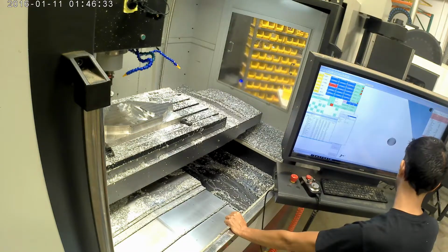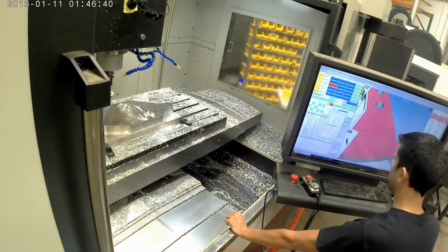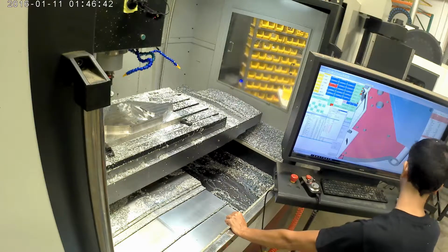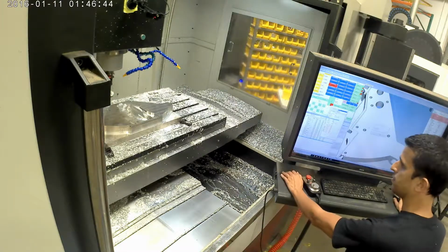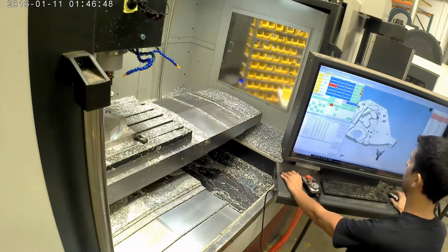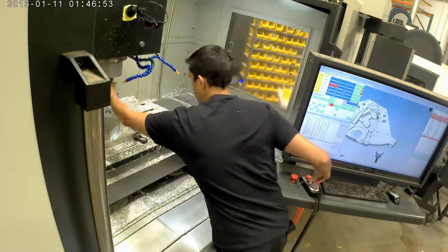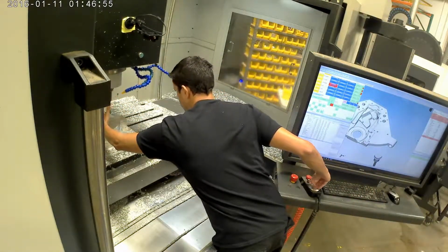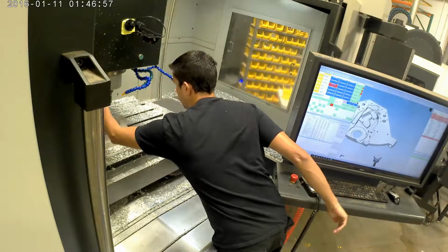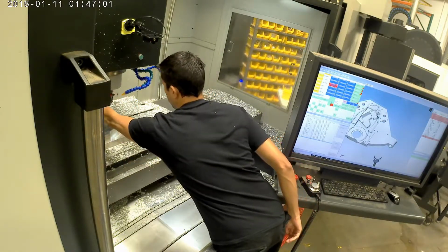And so now I'm going to go over to the right hole and repeat that same operation. Just click on the circle or the arc there, and then on the interactive page, just tell the machine to move to that XY location. And it moves exactly to that center point. And again, just drop the Z down into the hole and check it. And likewise, nothing has moved over here.